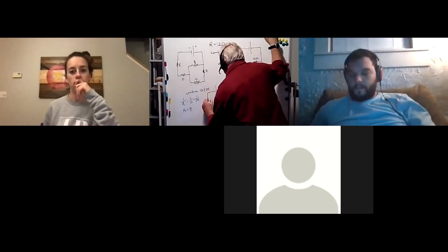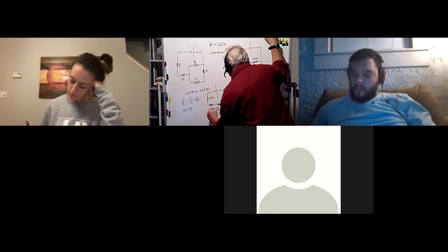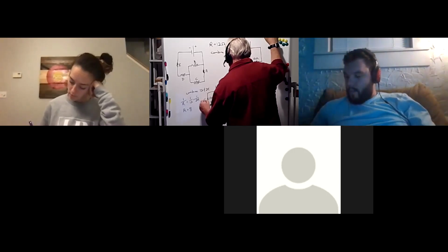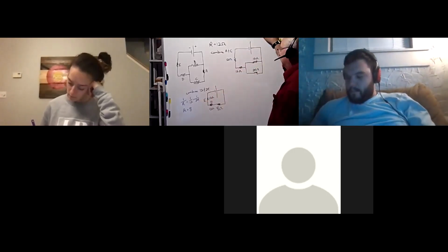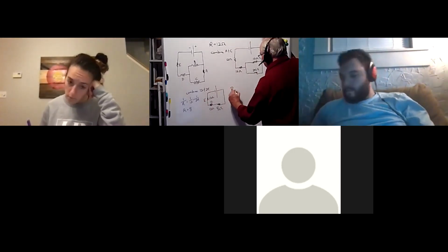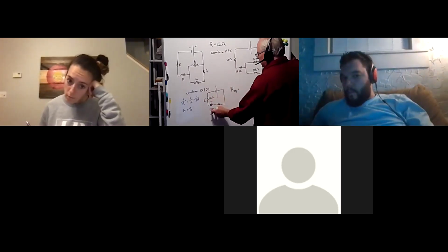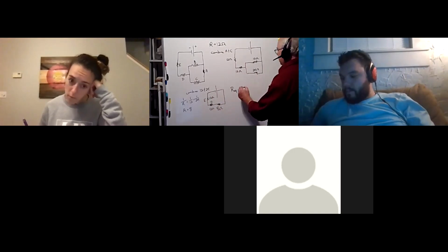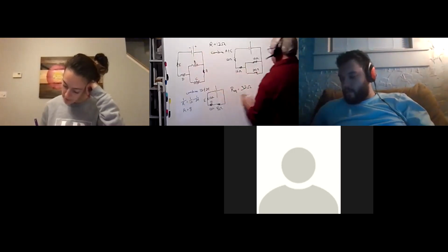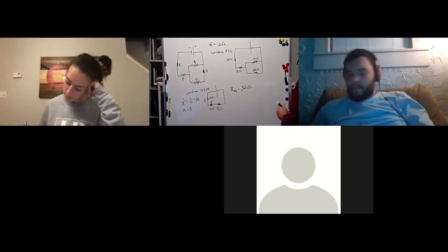And so we have 12 ohms and 12 ohms. Right, these are our originals. This is D and E. And now I just have a single pathway. So clearly these are all in series. So my equivalent resistance is equal to 12 plus 12, which is 24, plus 8, so that's 32 ohms. So all of this gets reduced. In general, I'll call this circuit reduction, gets reduced to 32 ohms.